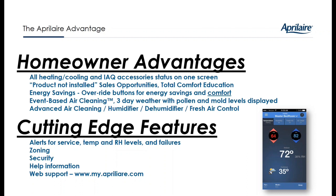We'll talk about some of these a little bit later, but not just from a monitoring, but also from an information standpoint, we allow the consumer to set alerts. These could be for service. The contractor could also set these up. For high temperature or low temperature, for high relative humidity, low relative humidity, and if you have any issues with, let's say, a remote temperature sensor not reporting back. The high and low temperature and RH are particularly nice if you have a home that you're not currently in.